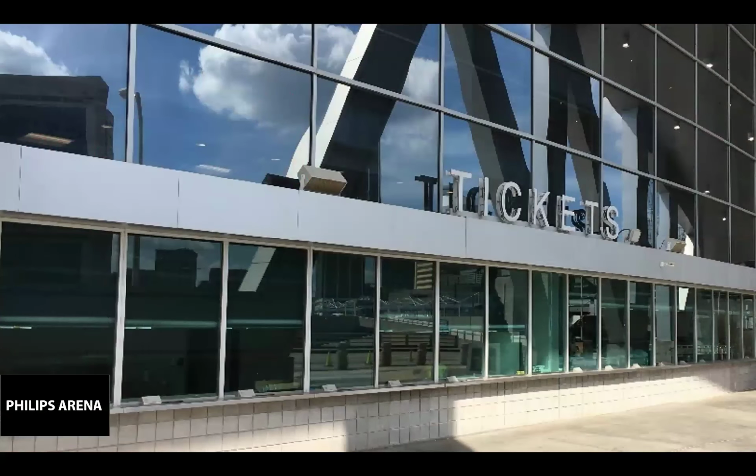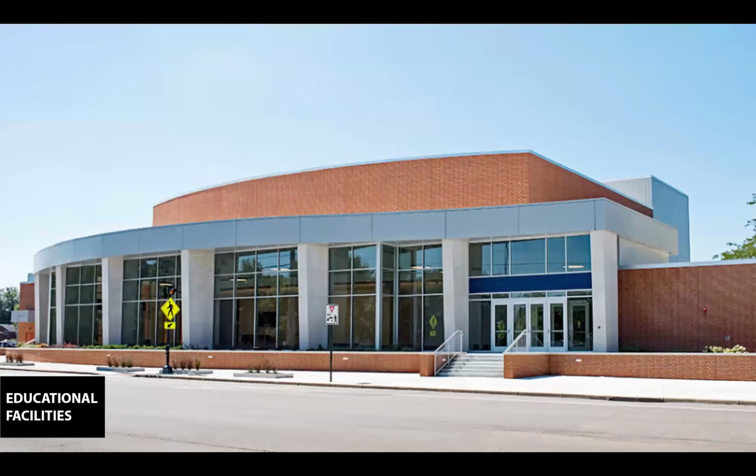So as we roll through the rest of these different types of images and project gallery and case studies, just by looking at all of these images, no one's going to be able to tell me if they're security rated or not, even just looking at this school right here, because I can tell you those doors and the storefront on the entry vestibule are all ballistic rated, level 3 standards, enforced entry rated. But the rest of the curtain wall and storefront going the other direction around the building was also rated as well, because if those assailants, gunmen, or crazy individuals are trying to break through the doors and they're not going to be able to get through there, the next place, look at that hallway, they can easily enter into that occupied secure space if they were just to break the windows on the first floor.